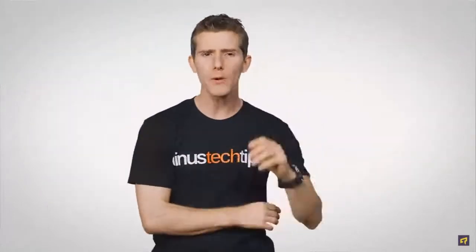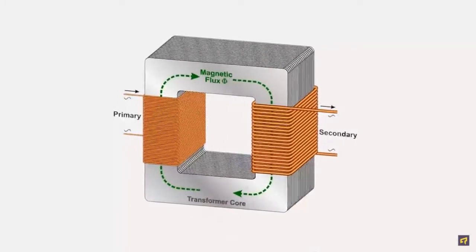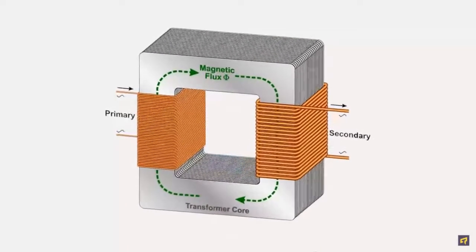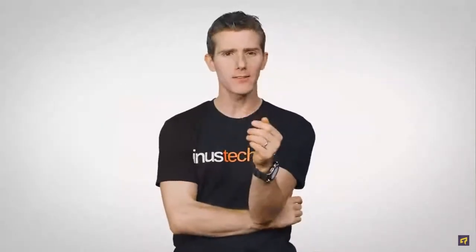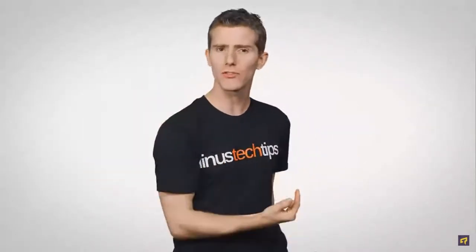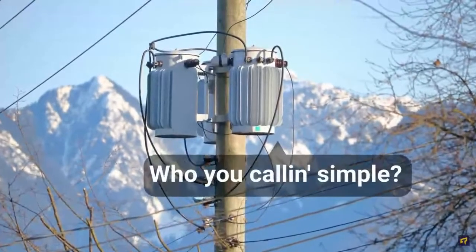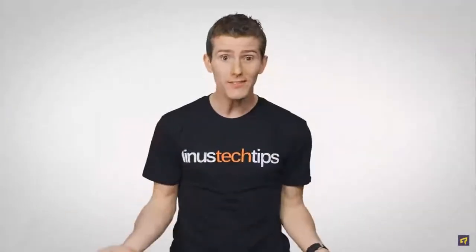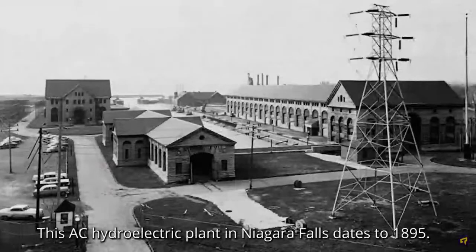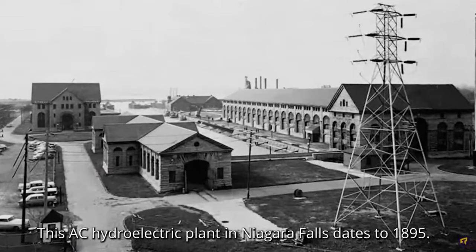Now, because AC power is changing direction all the time, this creates a changing magnetic field inside the transformer that induces a current and allows the transformer to work. In a DC system, the current is traveling in the same direction all the time. So those simple, inexpensive transformers that you see in AC systems simply won't function. This is part of the reason that AC became the dominant method of power transmission a long time ago and remains so to this day.